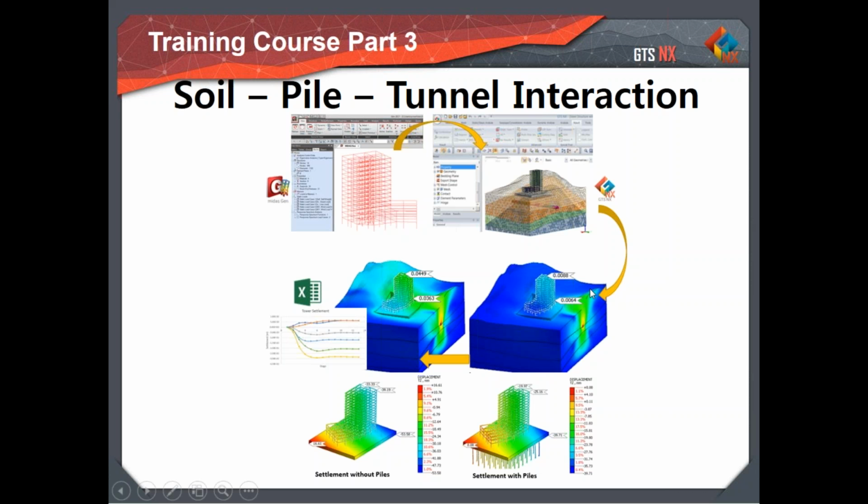Or it could just be, if it's an urban project, they want to make sure that this new excavation is not affecting the structure too much, or if there needs to be some sort of additional consideration or reinforcement, that kind of thing. So it's very handy to use these kinds of interactions, because when you do point loads, you can't really consider the stiffness or the redistribution in the structure.